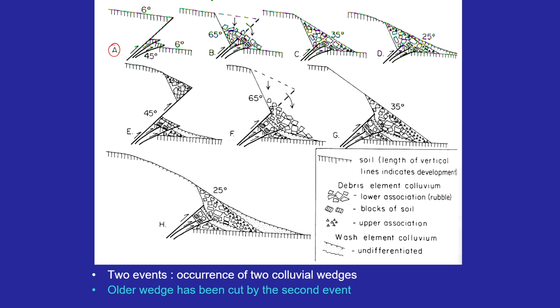Then after the formation of the scarp during an earthquake, in B it shows that there was erosion of this portion of the scarp, and then what you see is the deposition of the colluvial material. And finally, as we discussed in scarp degradation, the scarp will get stabilized as it reaches its angle of repose. Okay, so at 25 degrees it stabilized.